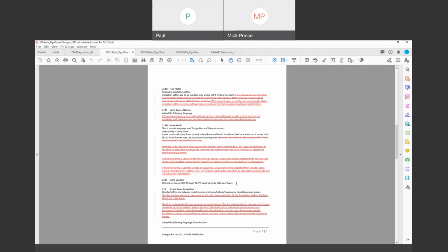So generally, Paul, there's not much going on back there, so it would just need the ignition barrier, the intumescent paint or whatever we're using for that. That would probably be the easiest. Yes. That stuff can be rolled on, or of course, it's really viscous stuff, so you'd need a really heavy duty paint sprayer to spray it on. Yeah, I've heard people spraying it on.